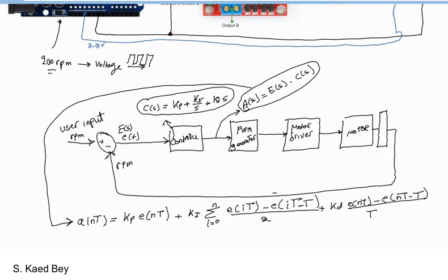It will try its best, but of course this will depend on your parameters, the Kp, the integral one Ki, and the differential component Kd. So in our Arduino program here, we will use the trial and error method just to optimize those parameters in order to achieve our objective. Our objective is to maintain 200 RPM as input by the user.